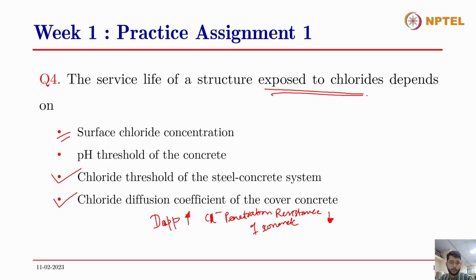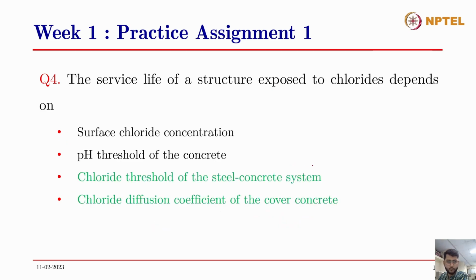Okay, all right. Talking about chloride threshold, we already know that. We have also discussed it in the previous question. If the chloride threshold increases, then the initiation phase will get longer, and hence the service life of a structure will be increased. But coming to what Dr. Satish has mentioned, the answer to this question will actually be the third and fourth, and not surface chloride concentration. As I mentioned in the last question as well, surface chloride concentration has nothing to do with the inside corrosion process of the structure.